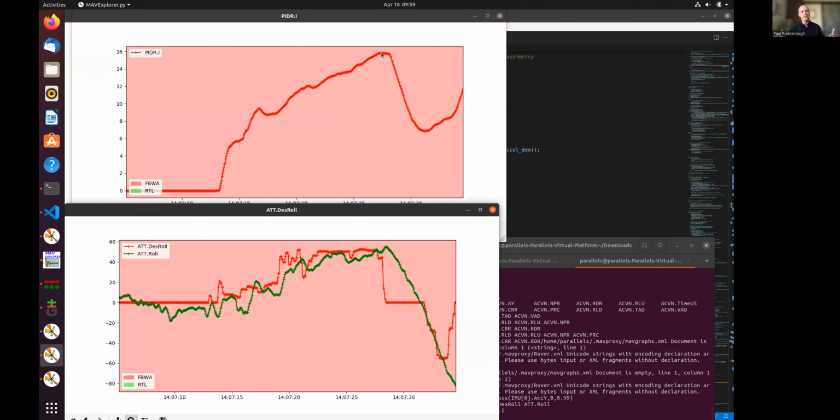Now this is a high wing aircraft, right? It's got what you call side slip stability. It's got a rolling moment due to side slip. So, it's side slipping to the right. Essentially it's got its nose to the top of the turn while it's turning right. It's generating this side force, and that side slip is trying to roll it out of the turn. So the aileron is winding up into the direction of the turn. Then when the pilot releases the stick, that integrator's got to come down again. And then they go back the other way, and eventually it loses roll control.